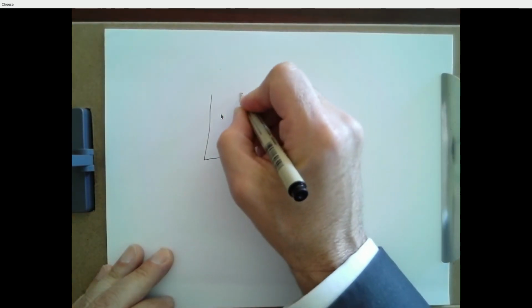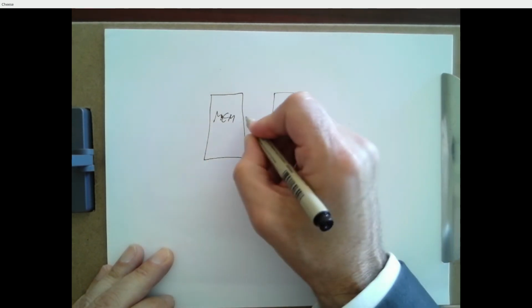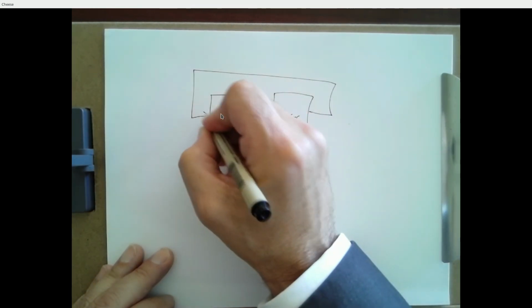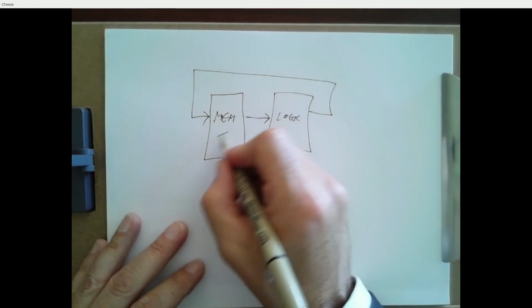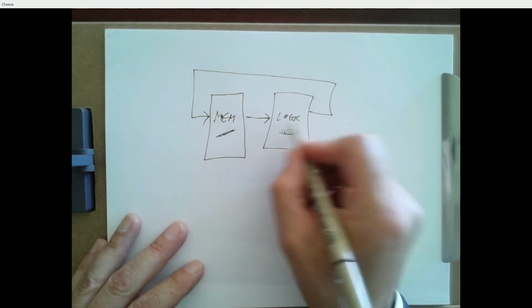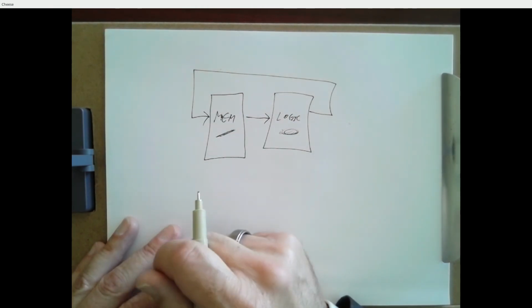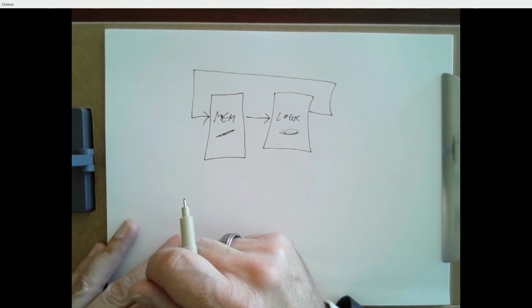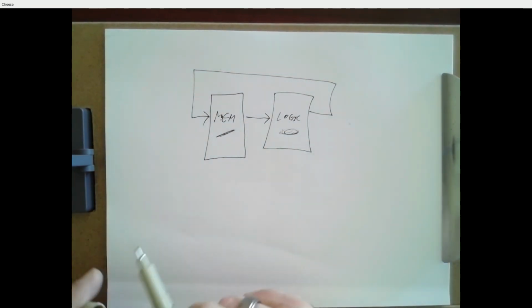Yes, because remember the general picture of our state machine. We have memory. We have logic. Memory goes into the logic, feeds back into the memory, right? The feedback makes it a sequential system. So there's a limit to how quickly we can change the inputs on this. And there's also a time that it takes for inputs to the logic to turn into valid outputs. So we'll run through that problem in detail after break and see how those numbers play out. And it's mainly going to be the setup time and the logic time. And the hold time kind of gets overwhelmed by those.